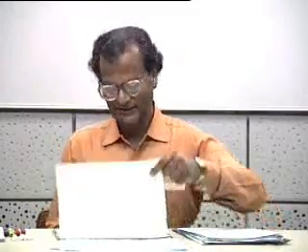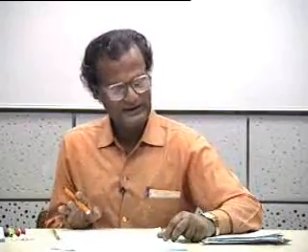What is H of 0? Capital H. What is the numerical value? Look at the figure and tell me. 1, and therefore it is simply x naught. It does not require any integral evaluation. A DC passes undiminished through an RC low pass filter.